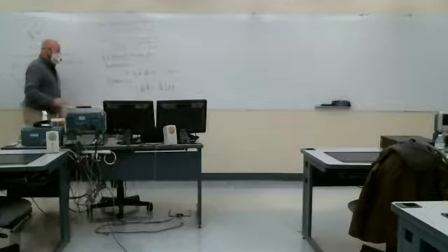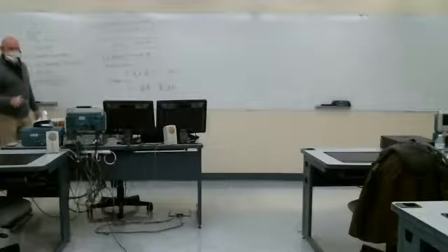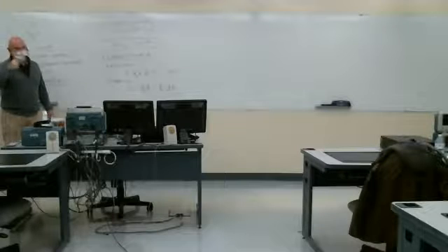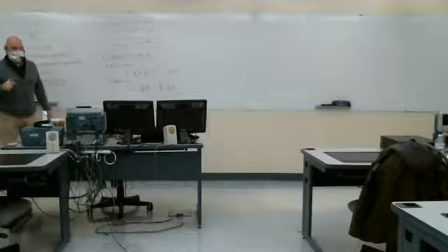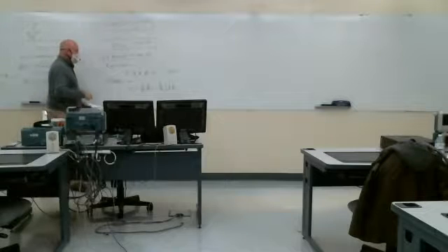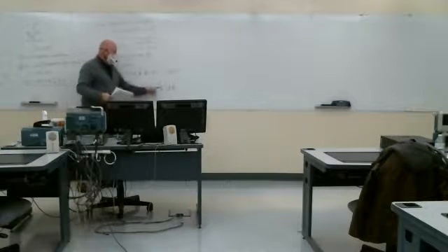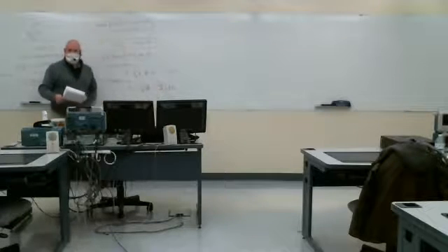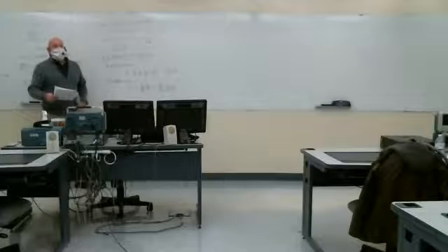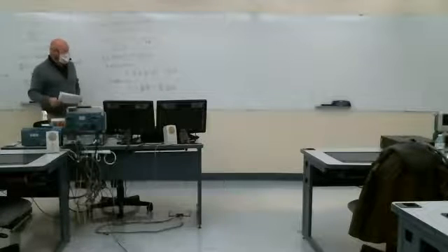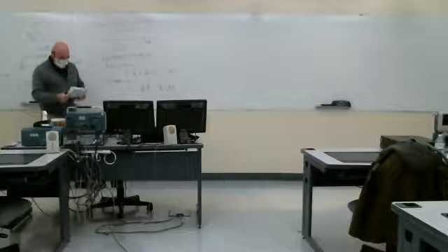Actually it says that the voltage around a loop, if there's a time varying magnetic field, again, we don't have this typically in circuits, so Kirchhoff's voltage law is valid within our circuits. But Faraday's law says that if we've got this time varying magnetic field, Kirchhoff's voltage law is really no longer valid. Okay. There is voltage generated around a loop.